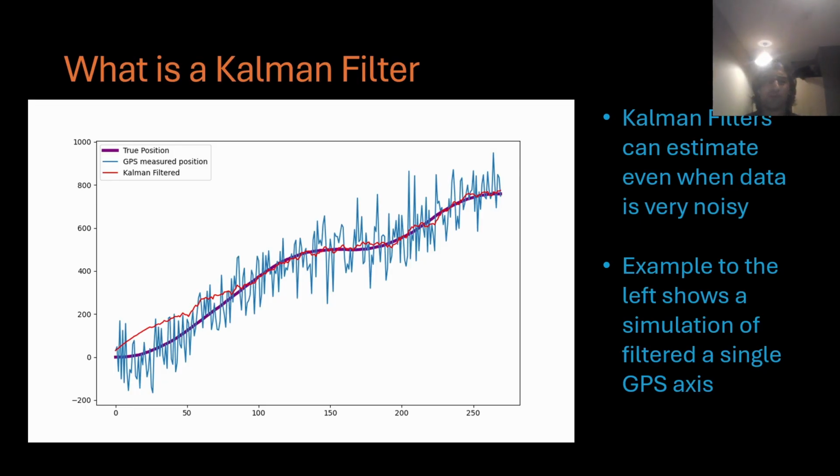Now this is a very simple example of using GPS with high frequency jitter, and it's simple because Kalman filtering can deal with this very easily. These little spikes, Kalman filtering will happily deal with, but there are a lot more complex examples where Kalman filtering has to deal with low frequency biases and drifts, not necessarily failures in the sensor, but areas where the sensor struggles a bit, and Kalman filtering can deal with a lot of these things. This is just a very basic example.